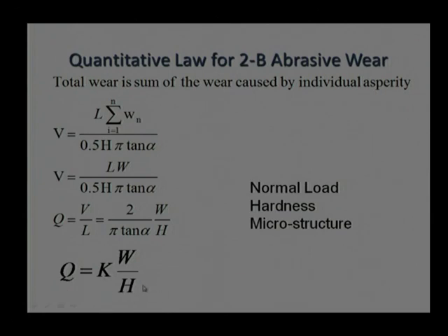In case of the ceramic material, we need to find out whether the material has that much energy absorption capabilities. If energy absorption capabilities is not there, even increasing hardness is not going to help us, because wear phenomena will change. It will cause some more fracture of the surface compared to abrasion.